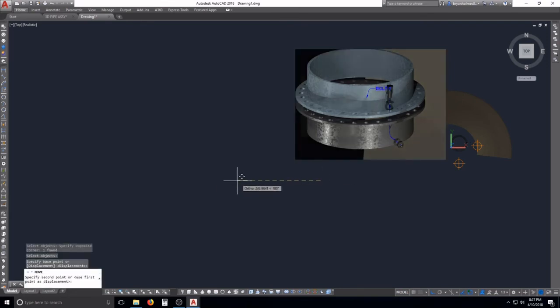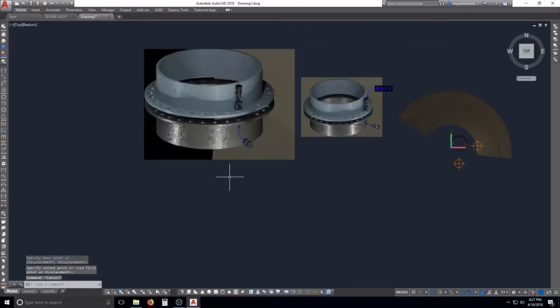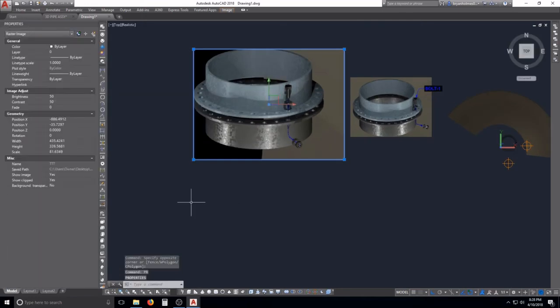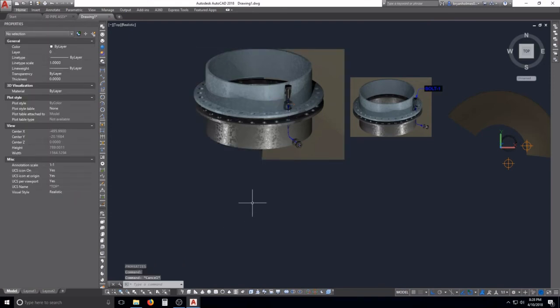And you say to yourself, well Brian, I thought you said that background would not show up. Well, it doesn't. If you notice the image, the frame around that one's gone as well. Once you type that in, that's for all photos. Highlight your object, or your photo rather, and type in PR, enter, get your background transparency. Yes. There you go. Neat little way to clip your stuff.